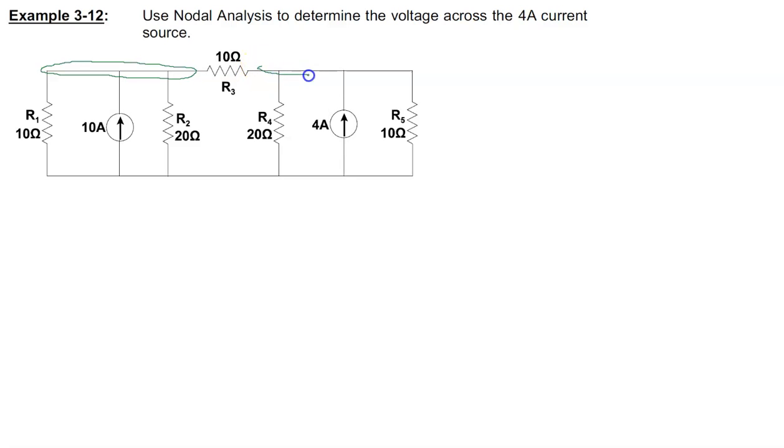All it is here is at the same potential. And so that's a node. And we've got this R3 in between them. Across the bottom of our circuit then, all it is here is at the same potential. And so this is our node. And so really we have 3 nodes in that circuit.